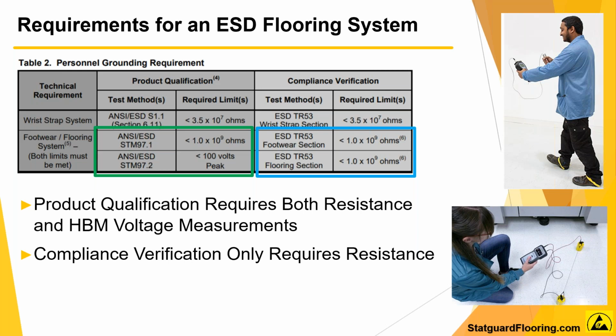In the 2014 revision of the S20.20, the resistance method of qualification was eliminated and a walk-in voltage test was required for qualification, regardless of floor resistance. Specifically, the standard covers the requirements necessary to design, establish, implement, and maintain an electrostatic control program for electrical or electronic parts, assemblies, and equipment susceptible to damage by electrostatic discharge greater than or equal to 100 volts human body model.